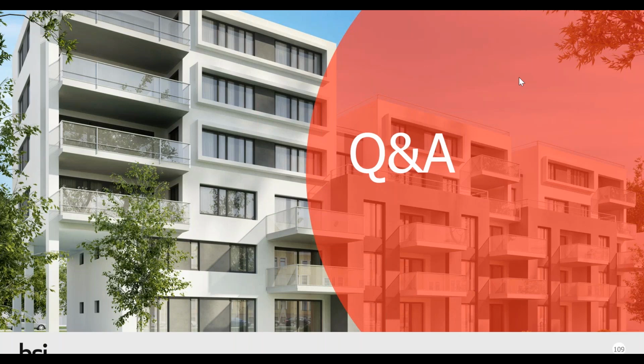Why use laminated glass? Well, safety is the obvious answer to that. In some countries, laminated glass is mandatory. On balconies in the UK, that's not necessarily the case. Designers need to consider the risk of injury and death from falling, from a post-breakage scenario of a broken non-laminated guarding, versus any risks arising from fire.